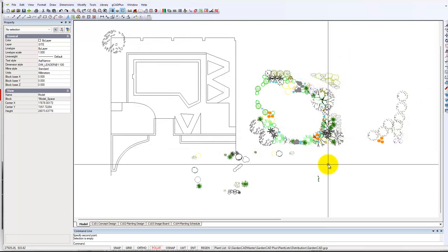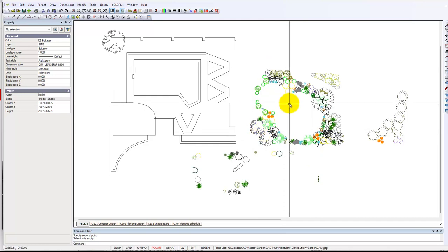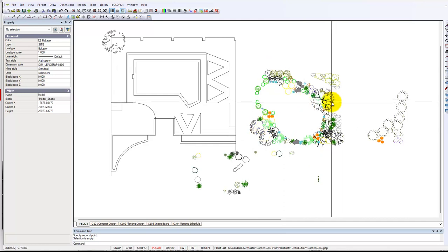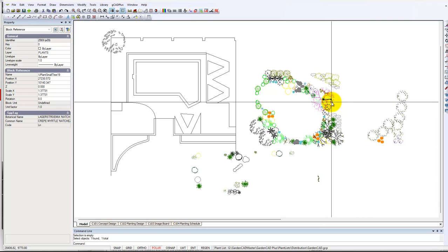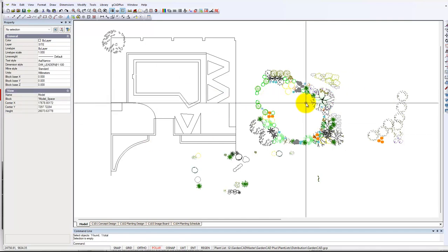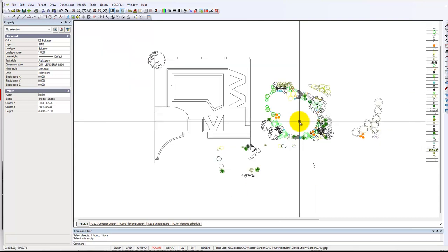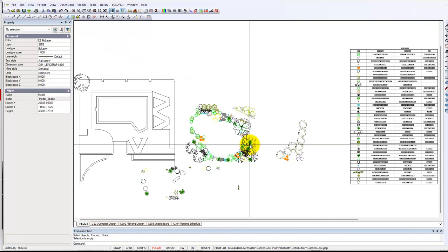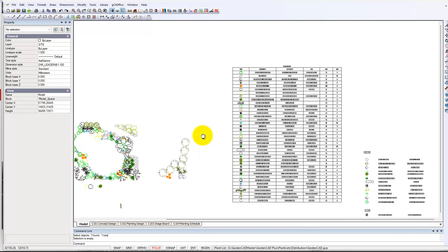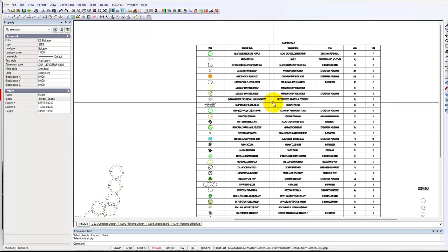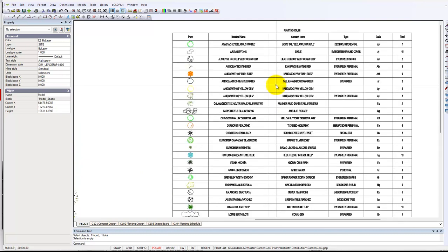The symbols that you see here, while they are somewhat sized, this is probably a tallish deciduous tree. It is the crepe myrtle. It's not easy for someone else in the office to use this template. What I would suggest, if you're in this situation, is to run the plant schedule tool and run through the generation of a custom one.